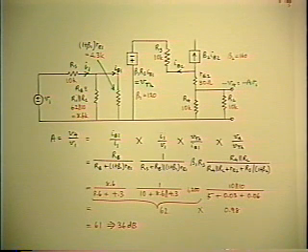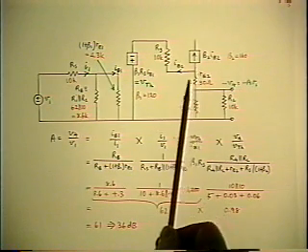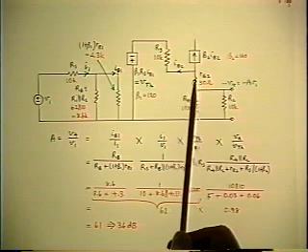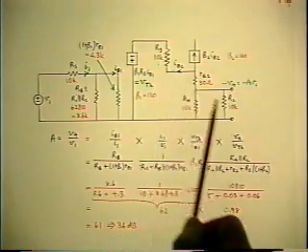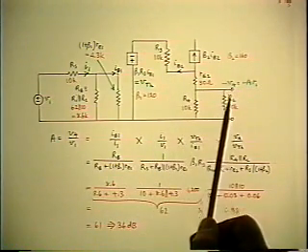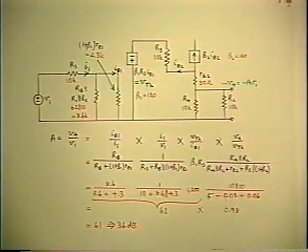It's sort of like half a transformer. A transformer transforms both voltage and current according to the turns ratio. A transistor transforms current by a large factor, but voltage 1-to-1 almost. Which is why impedances reflect according to the current gain and not the ratio squared.